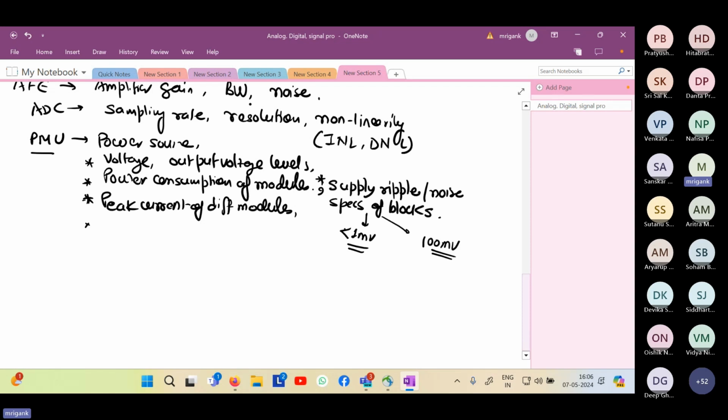All these things depend upon how robustly the analog front end is designed, how much noise it can handle, and also what the minimum signal amplitude it is supposed to sense is. If the signal amplitude is very small, say 10 microvolts, then the power supply constraint will be even more stringent. The supply needs to be much cleaner. Some special power management technique has to be used.